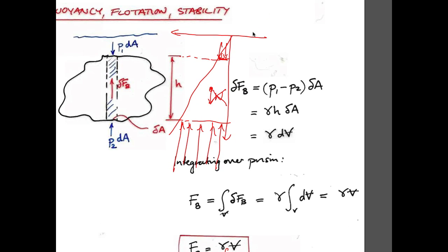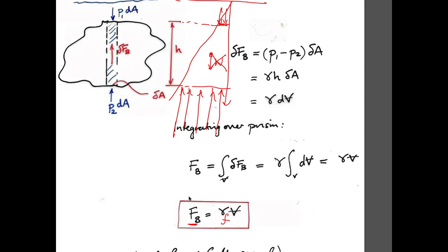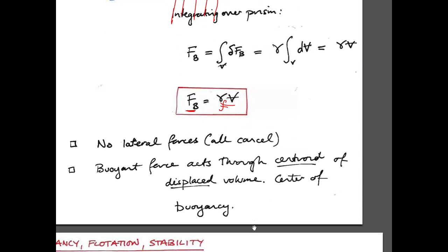So we can use this idea of an out-of-balance force to evaluate the force that acts on structures. In the same way that we calculate resultants, for instance, to calculate whether a gate opens, this is also an extra additional component that would act on submerged bodies. The only important thing to remember is that this buoyant force is really an out-of-balance force that we have to restrain, and that the unit weight that we're dealing with is not the unit weight of the material that's removed from the system, but the displaced fluid and its volume. So it's just Archimedes' principle.